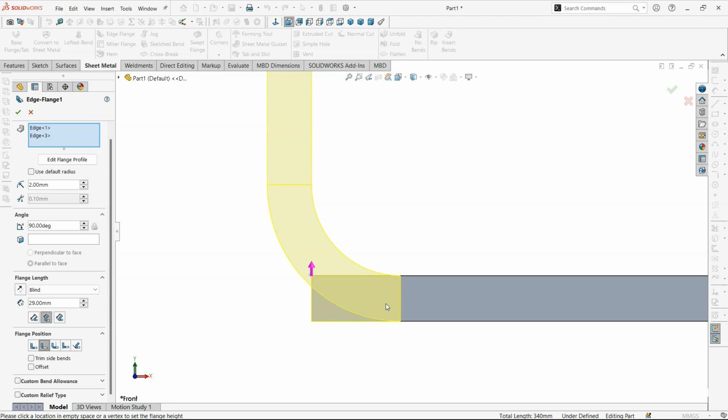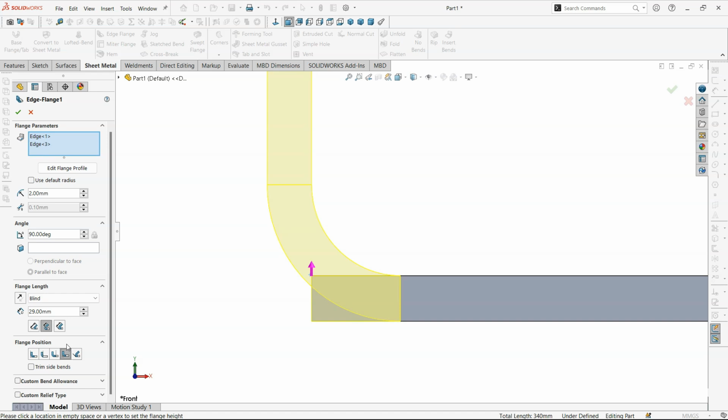In the second, the bend is currently inside, but this material part, this rectangular portion here, is collinear from this line. Third, the bend is also outside. Fourth, you see here that this point, the center point of the radius, is coincident to this point. Currently both here are the same.